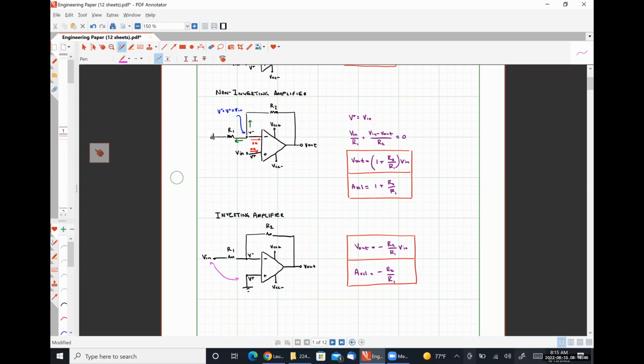That's literally the only difference between these two circuits, but we get very different functionality, even though there's only a subtle change in the topology, right? And it's because we're applying the input signal to the non-inverting input terminal on one and the input signal through our feedback network to the inverting input terminal on the other. So we have to be very, very careful about how we construct and design op-amp circuits, because one small change in our circuit topology can have very large effects on how the circuit itself behaves.